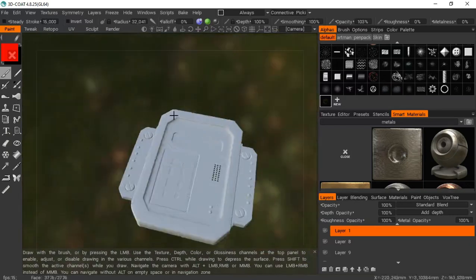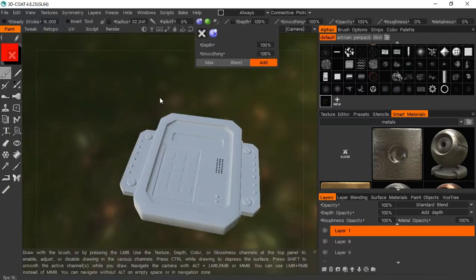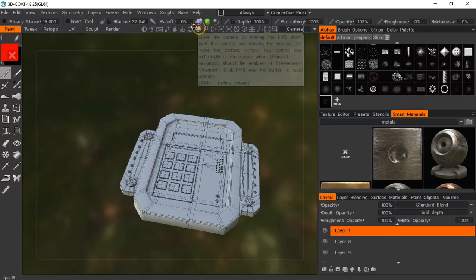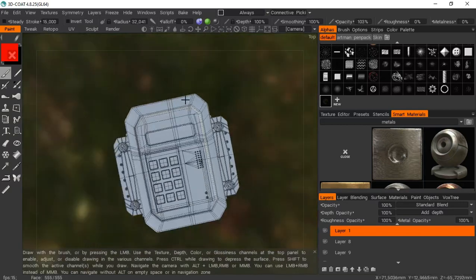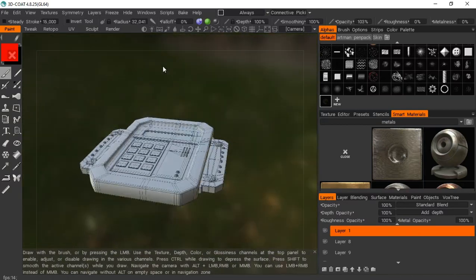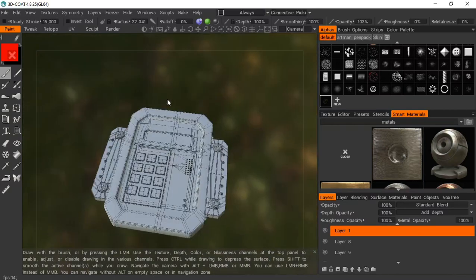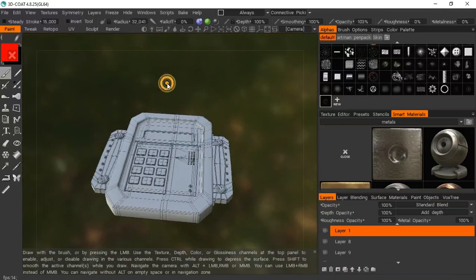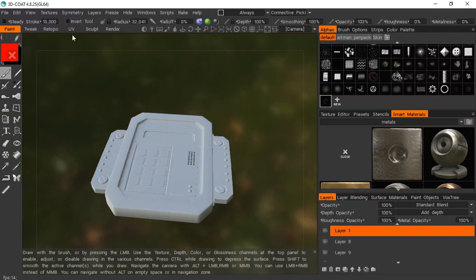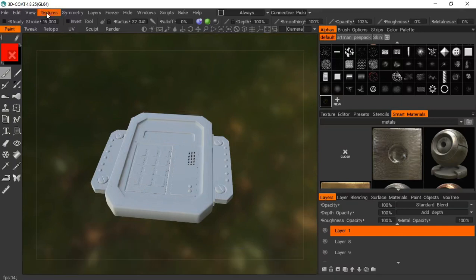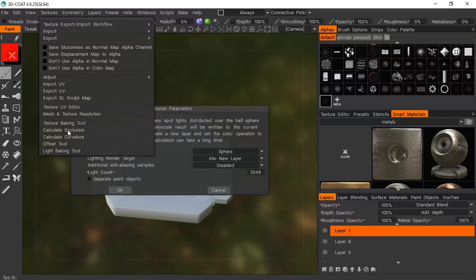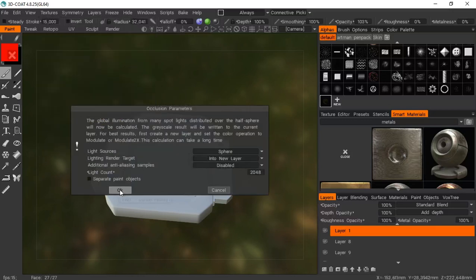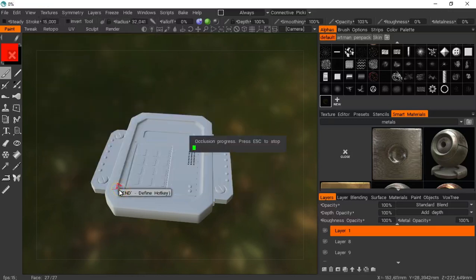It's freshly here. So you can press the number 4 to see your model's wireframe mode, and it's going to show you your geometry, your lines. So far I like my model's wireframe, my geometry. It's really good. So you can press 4 again to remove that, and then you can come to textures up here and click calculate occlusion. This has to always be done because your PBR painting needs to know where the shadows are on your model. So we can just wait for that.